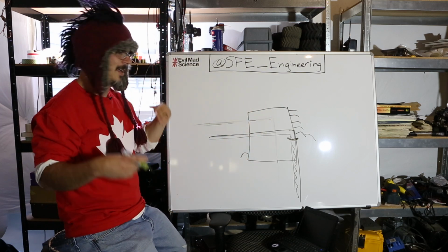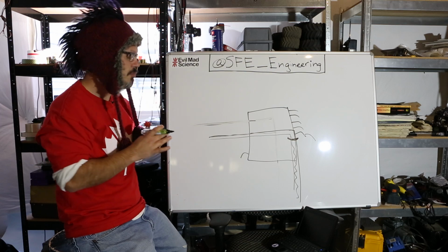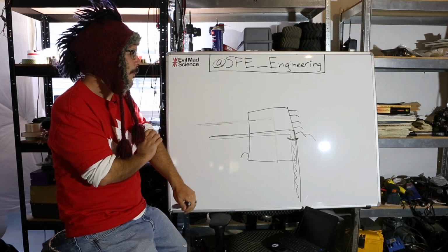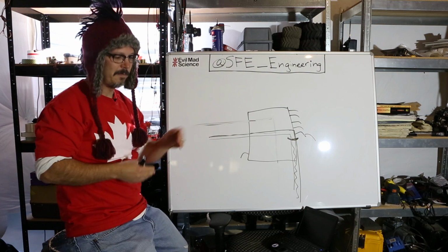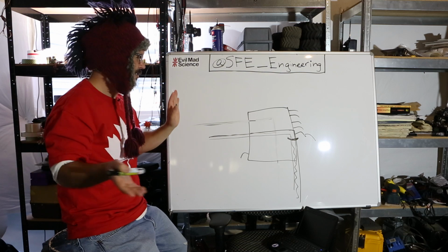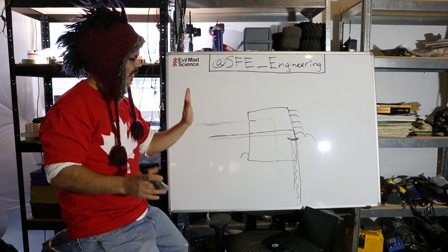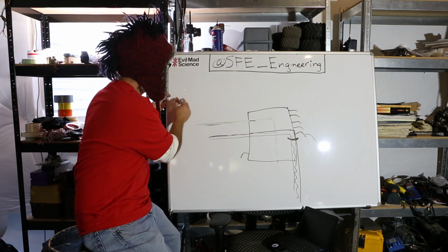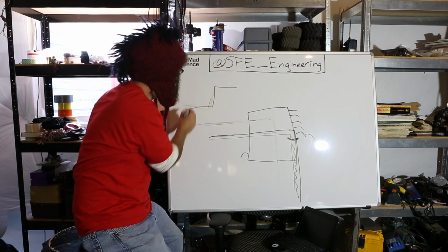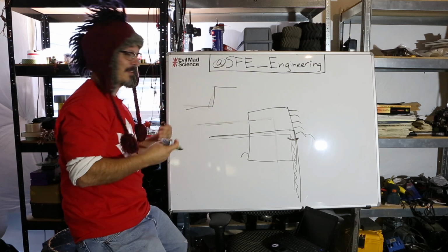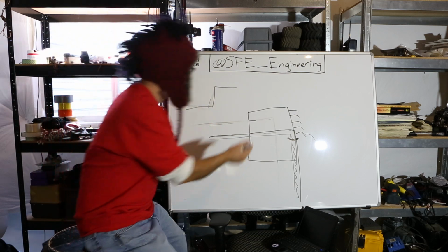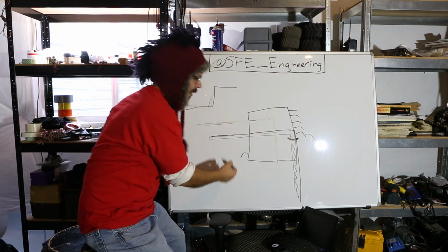Digital communication and digital function in general, and I've explained this in previous videos, when you're running a square wave, that edge, everybody think back to college days, if you've been to college, the edge has a lot of harmonics. So the sharper that edge is, the more high-frequency harmonics are in that thing, and that's noise, right? So you want to keep that kind of junk out of your analog section.